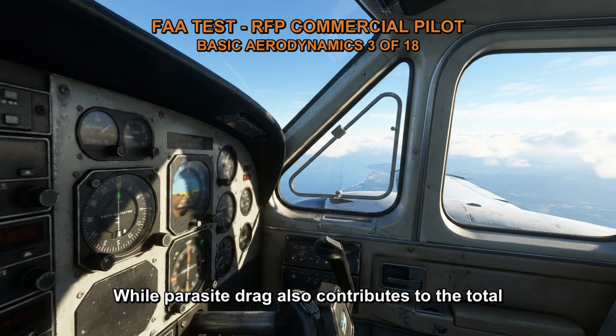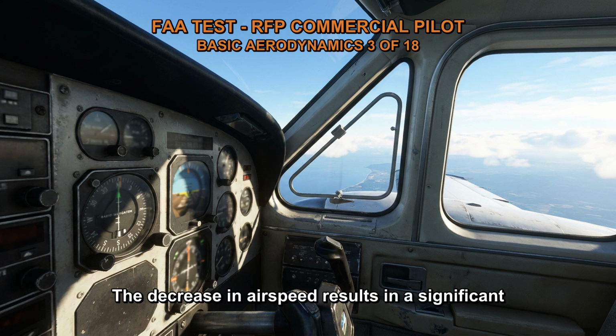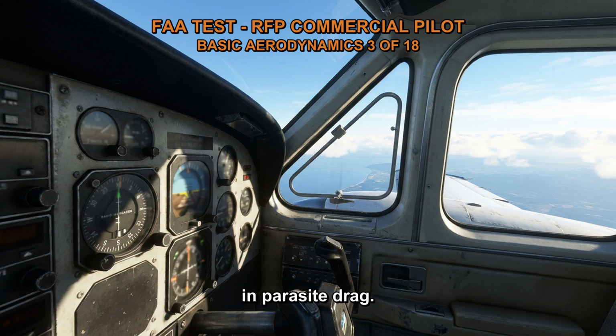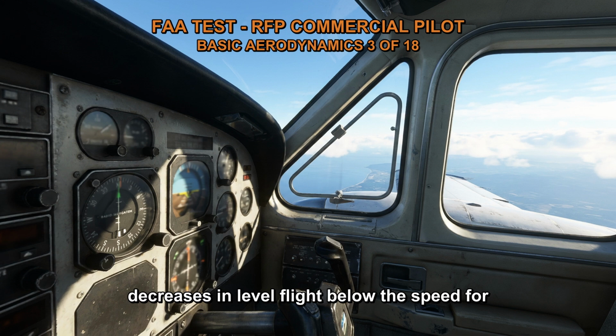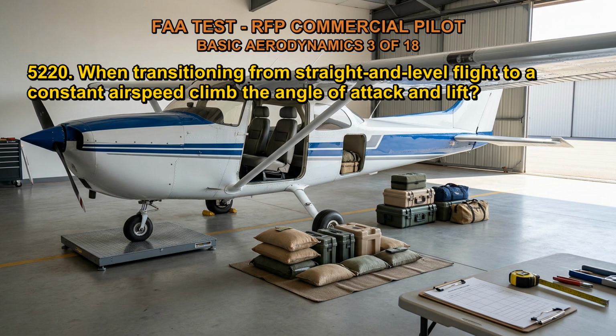While parasite drag also contributes to the total drag, at lower airspeeds, the increase in induced drag dominates. The decrease in airspeed results in a significant increase in induced drag, outweighing any potential decrease in parasite drag. Therefore, the correct answer is that as airspeed decreases in level flight below the speed for maximum lift/drag ratio, the total drag of an airplane increases because of increased induced drag.